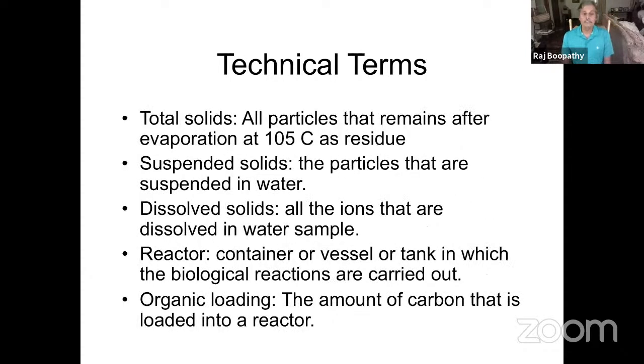The next definition is a lot of solids also. When you talk about wastewater, you need to know how much solids go in there. So we have total solid, suspended solid, dissolved solid. The regulatory agencies make standards based on how much solids are in the water, because the discharge water should be as clear as possible. You don't want to have turbid water going in there.